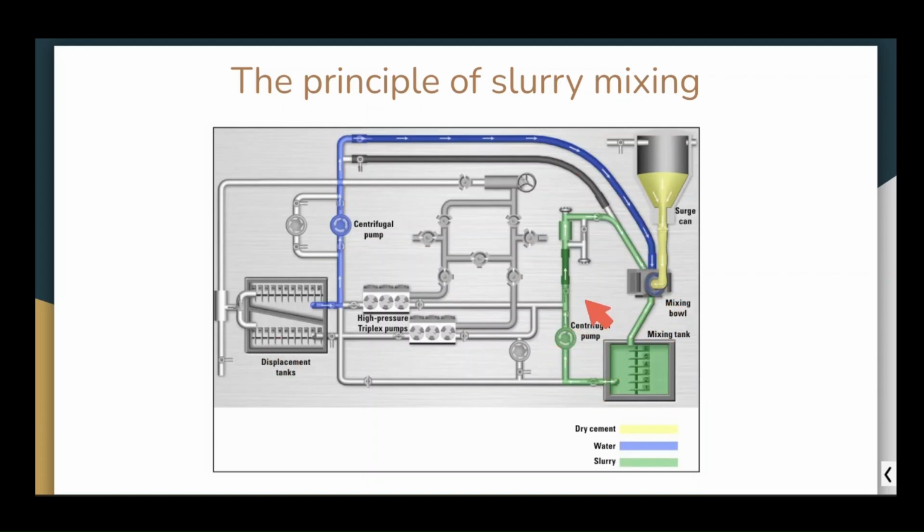Then this is the centrifugal pump for recirculation. This is a centrifugal pump. This is an additional centrifugal pump, like a backup centrifugal pump, or also to take fluids from drill pits and flow into the high pressure triplex pump, maybe, or a mixer system. Also we can circulate if this centrifugal pump malfunctions, so we can use the additional centrifugal pump to mix our fluid. Also, as I said, the centrifugal pump takes water, takes drill mud, and feeds the high pressure triplex pumps.